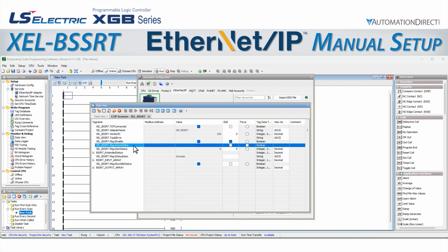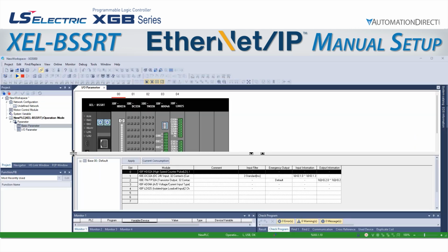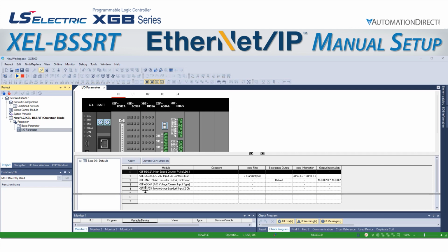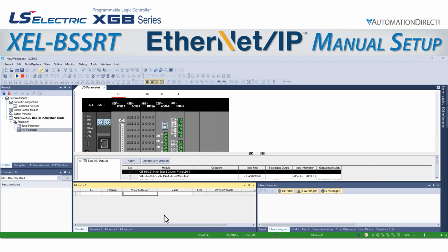We get the TCP connected return, the software populates the adapter name and vendor ID, and the connection online boolean also becomes true. Let's try and turn on the first output of our digital output card. If we go over to XG5000 and then to the I/O parameter screen, which is already open in our case, we see that the TN32A output card is in slot 2, which is the third slot, and that the first output point is variable %QX0.2.0.